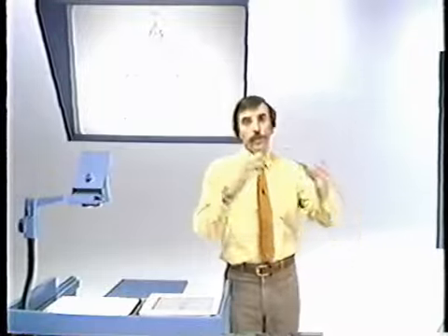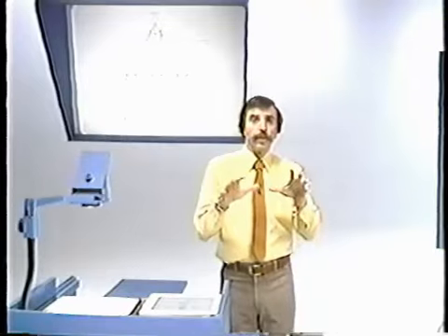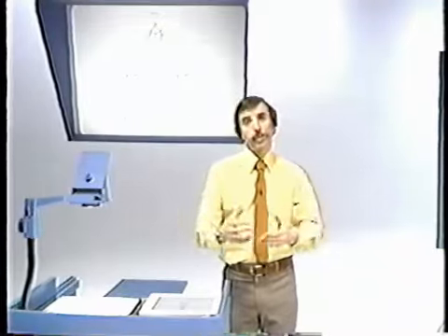Okay, now what we can ask is, we've got this processing, we've converted to discrete time, and we've gone back to continuous time, and one can ask now, what equivalent overall continuous time system does that correspond to? In other words, that of course is a continuous time system, a continuous time input and continuous time output, and the overall system then would be one that would give us exactly the same output spectrum as we're getting. Well, what is that?